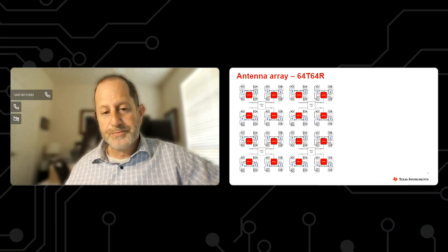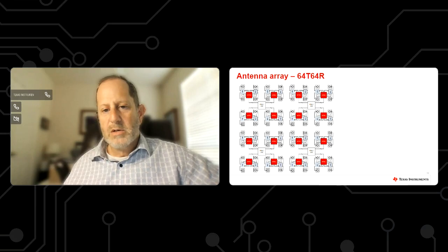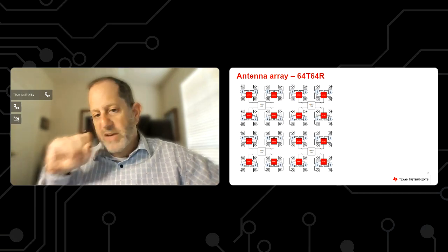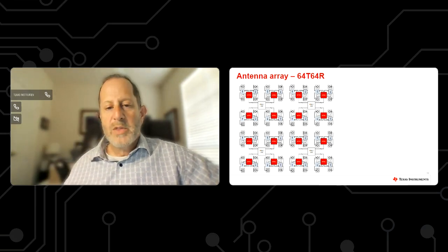facilitate that. So, for example, if you recall, I talked about that clock distribution chip that has some features that not only can we synchronize the dividers, like on our RF synthesizer parts, so if we have multiple synthesizers that are employing dividers, we can synchronize those outputs to make sure those are deterministic and in phase.